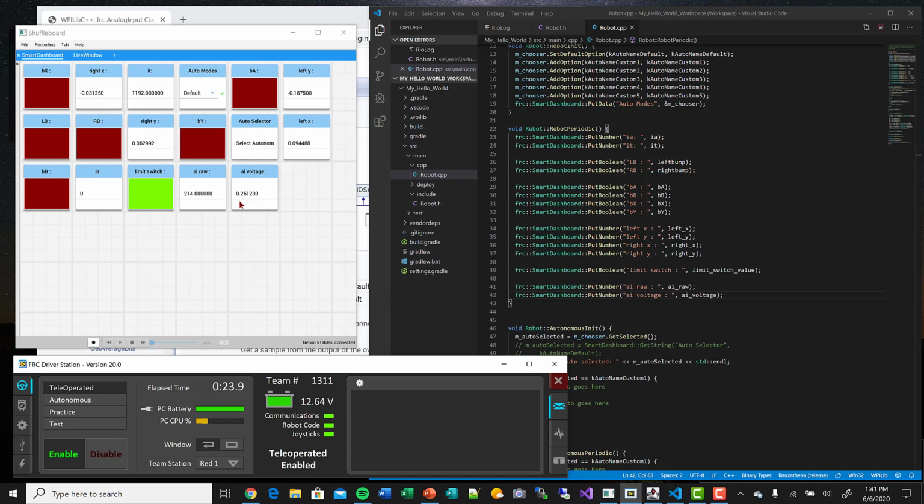I'm going to grab the 2 pins and just short them together with my fingers. There you go, that brought it a little closer to 0. What you're seeing here is a little bit of noise and other stuff that's being picked up, introduced to the front end of the analog to digital converter. So it's really hard to get to 0.